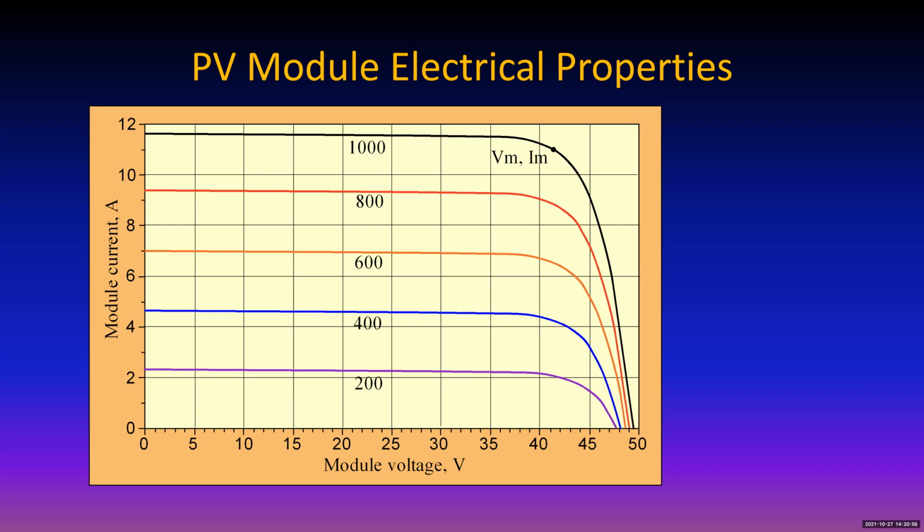So let's talk about PV modules for a minute. These are the things that make the electricity, and they have some very special electrical properties. For one thing, what's the best way to reduce the voltage of something to zero? Well, one way is to turn the switch off. Another way is to short it out, because then the voltage across the terminals is zero.